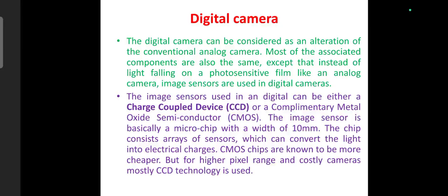On the other hand, CMOS sensors are less expensive to manufacture and consume much less power. Modern CMOS technology has improved significantly, and today most smartphones, webcams, DSLR cameras and mirrorless cameras use advanced CMOS sensors because they provide excellent performance at a lower cost. Therefore, the choice between CCD and CMOS depends on the required image quality, cost and application.